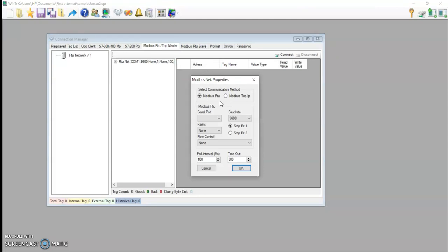Right now it's Modbus remote terminal unit. We are not going to use the RTU communication. We would be using the Ethernet version, which is the TCP/IP configuration. I have selected the TCP/IP configuration, and this is my default IP address for this system over here. And this is the default port that it will assign for your laptop, desktop, or whatever it is, right? It says there is a timeout of 500 milliseconds and a poll interval of every 100 milliseconds, right? This is how it will keep checking whether my established connection is fine or not, right? So these are the defined parameters over here.